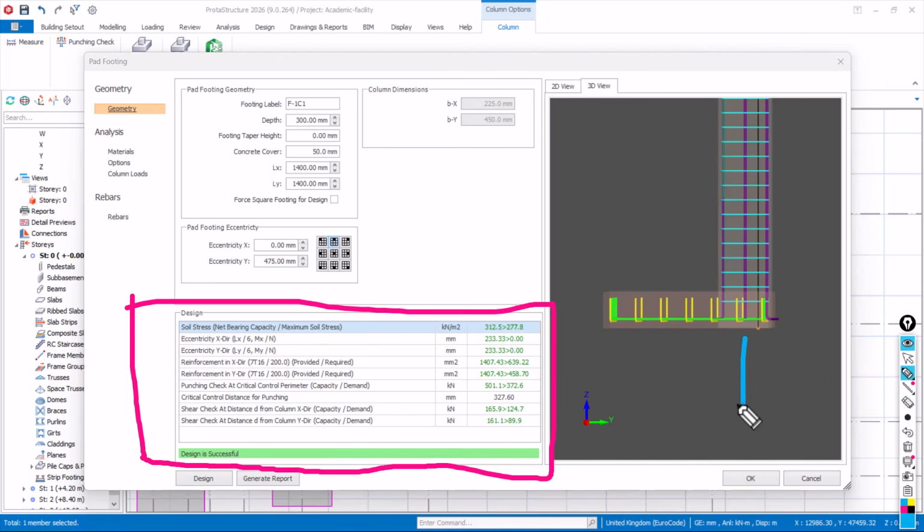Now, when the load acts here like this, what then happens to this other side? Because all the weight is on this place, it will cause uneven soil pressure. Since the soil under the footing is uneven, this place will have less soil, and more soil will be on this place, because the load is all here. When the soil becomes uneven, it will cause overturning or an uplift, because this particular side of the footing has less soil.